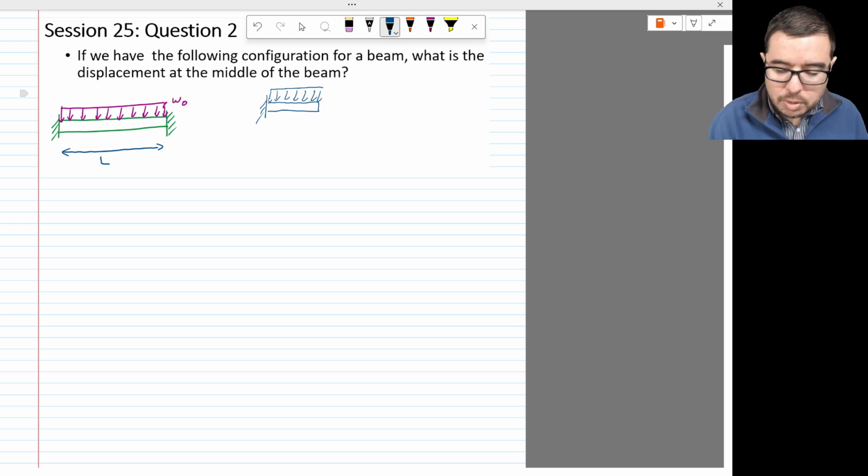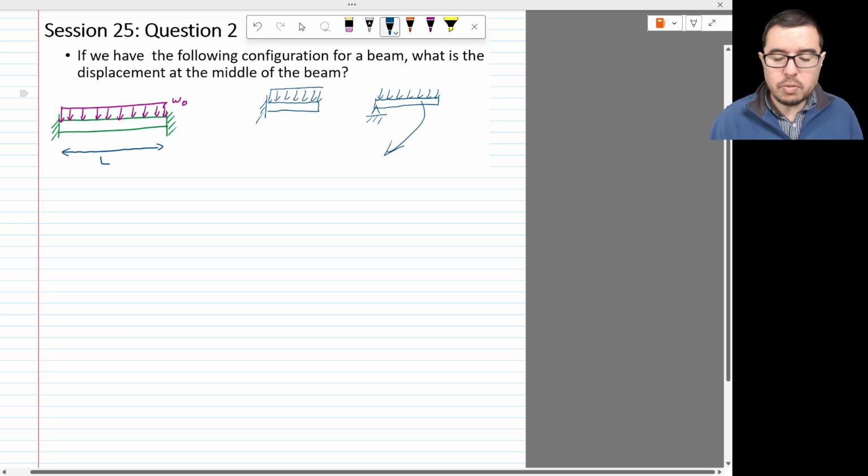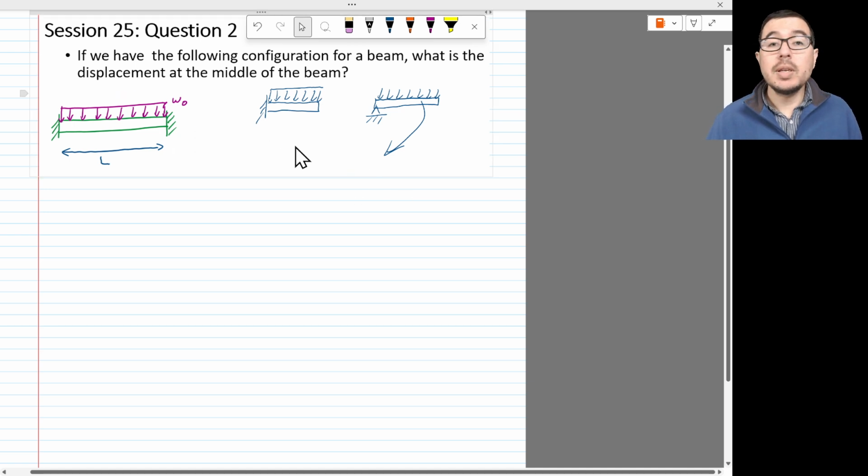But if I were to do something like this with the beam, and I removed an additional constraint, changing the wall to a pin, of course, this is just going to flop around like that. So we see that the beam with the walls on each end is going to be statically indeterminate to the second degree. Why?